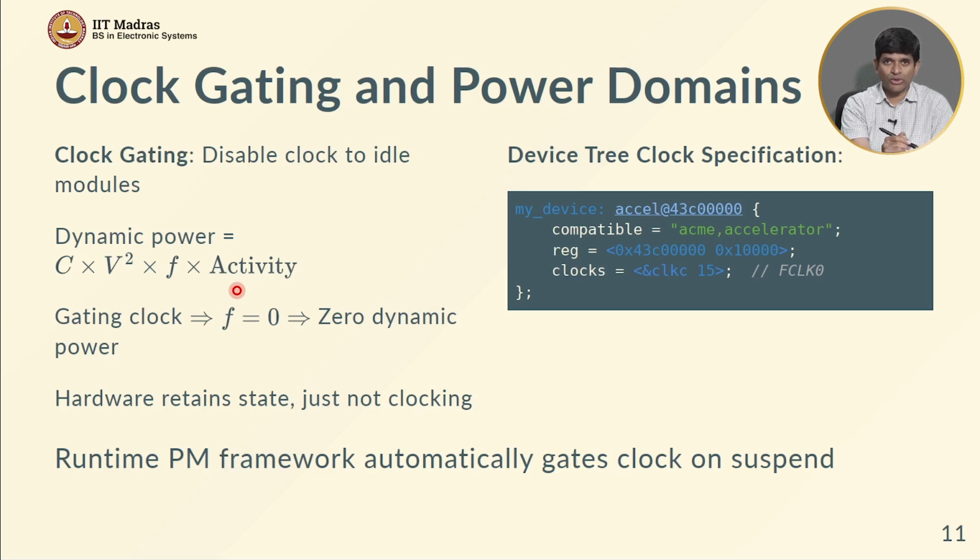So I put the clock through an AND gate, the other input of the AND gate I make it 0, and that's it, there's no clock coming out. If I make it 1, the clock signal directly comes through to the output of the AND gate. So literally that is why the term gating is used. You can in principle use something as simple as an AND gate. In practice it may not be a regular AND gate, it may be something that behaves like an AND gate but is specifically constructed for the purpose of clock gating.